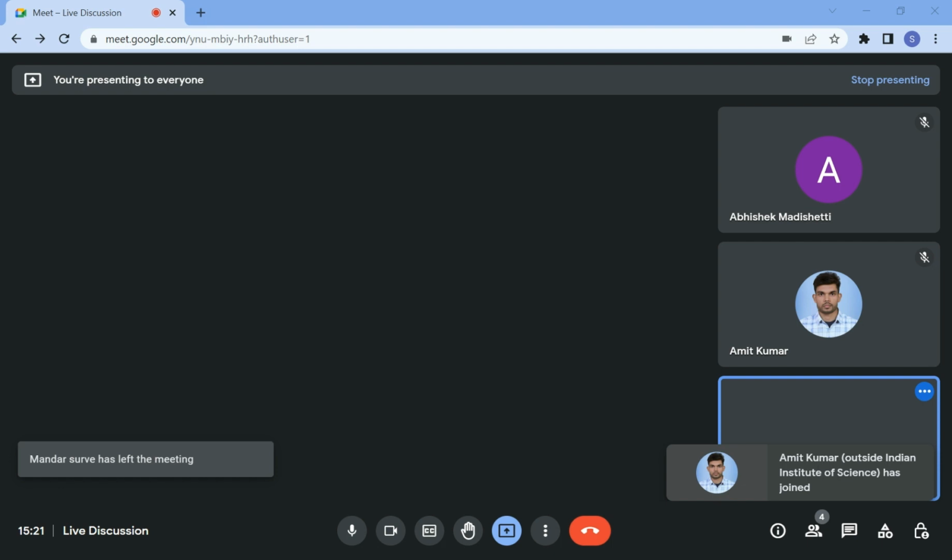So this front view makes 55 degrees. If you say front view, this is the front view. In front view, you will generally see the angle with respect to HP, but that is not the true angle with respect to HP. But given this information, we can directly say that okay, this is 55, with a note that this cannot be true length unless it is some special case.